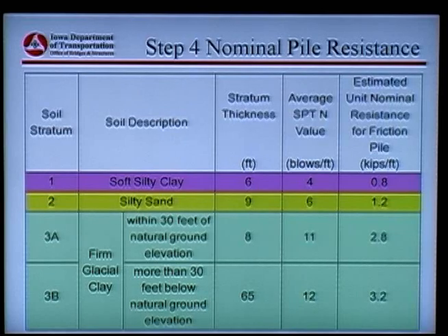Now, the next point down then is the bottom of the sand. So you'll see the next line on that frame in the top of page 6 was 6 plus 9, which is 15. There it is, 6 plus 9. And at that point, we take the sum from the previous one, which was 4.8, and we add to it 9 feet times the 1.2. And you'll see it in there, 9 times 1.2, which is 10.8 kips. So 4.8 plus 10.8 is 15.6.